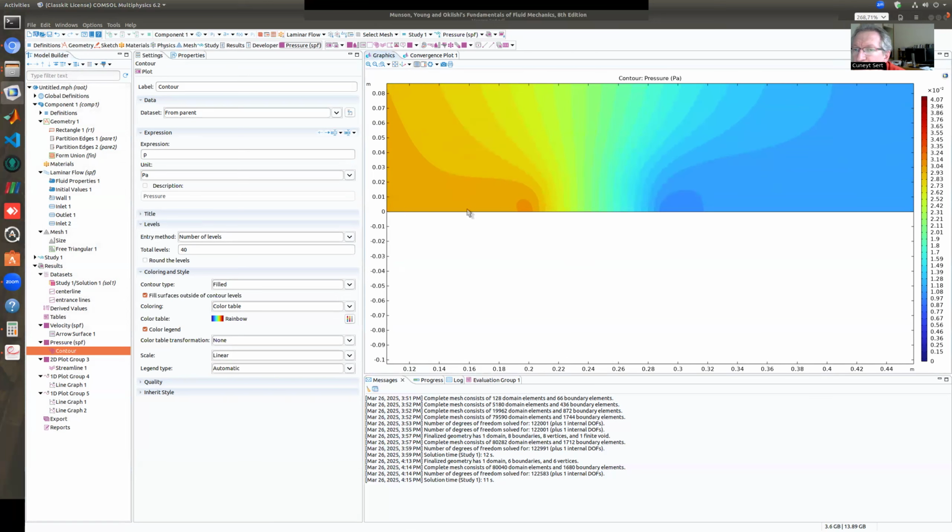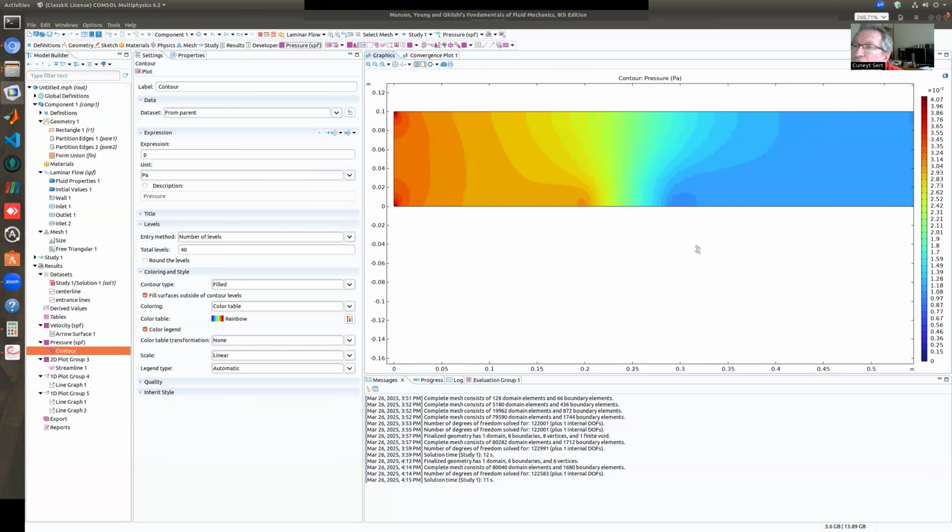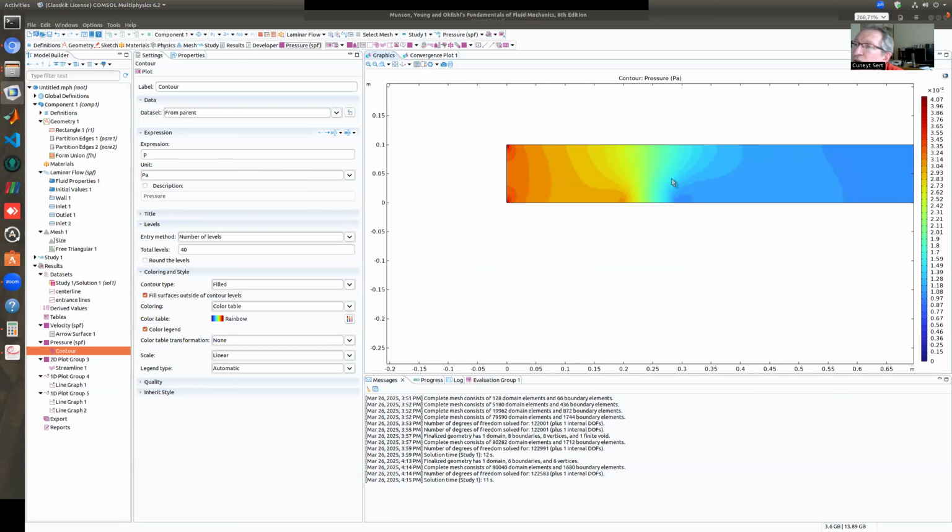A streamline is coming like this and then this is the start of the bottom entrance and then it just hits that vertical flow. So there is a right going flow and then there is an upgoing flow and then they hit each other, boom. And then we are creating pressure gradients. And a similar thing is also happening here. We have this kind of flow and then we have a little bit of maybe circulation here, I don't know. So we have interesting pressure variations.